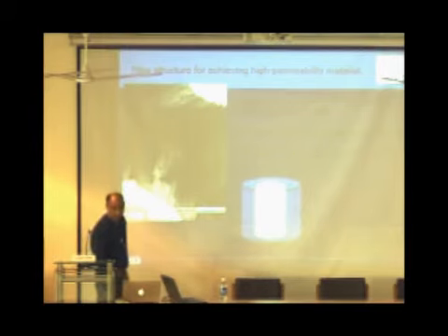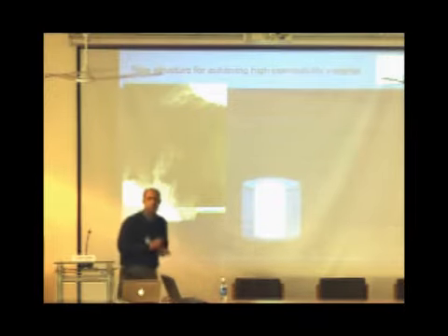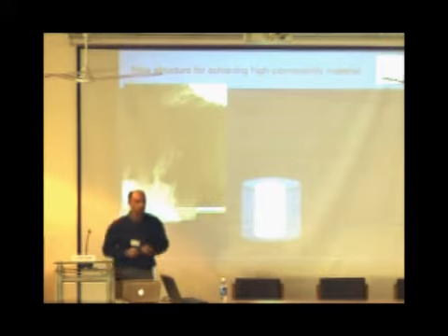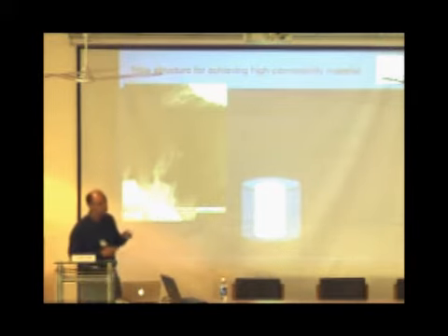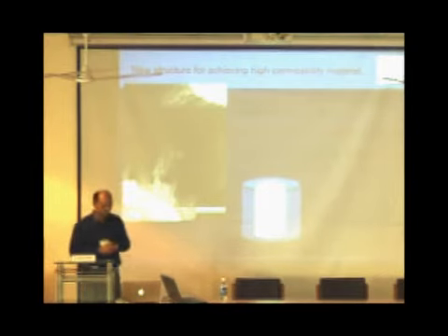So, we have actually made cobalt nanotubes using this deposition technique, which are 100 nanometers in diameter, outer diameter, and 50 to 70 nanometers of the inner core of these is hollow. And in the case of cobalt palladium multilayers, we get what is like a bamboo structure. So you would have nodes of palladium and then hollow tubes of cobalt stacked on top of each other.